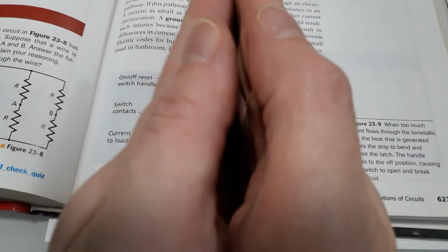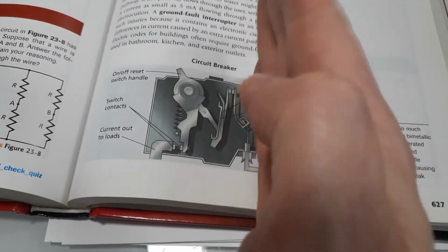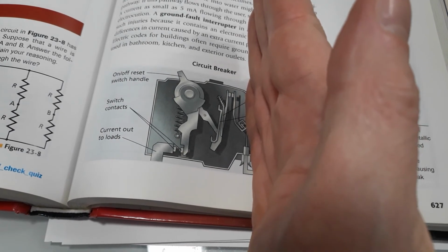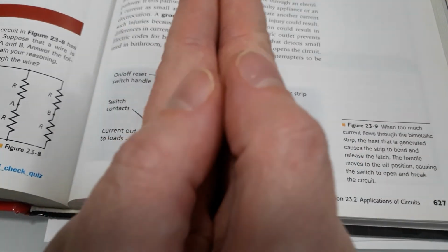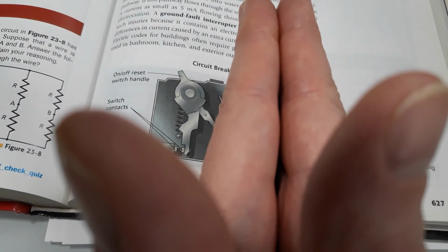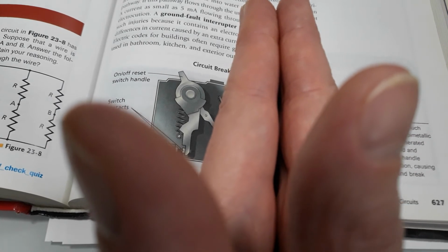So what you want is two different pieces of metal. Let's imagine that my right hand expands more rapidly than my left hand does. Well, when I connect these two together, even though my right hand is trying to stretch and get longer as it warms up, it can't go anywhere because it's connected to the other piece of metal. So as my right hand expands and my left hand doesn't expand as much, the piece of metal will begin to bend like this, because you can imagine my right hand is now following a longer path than my left hand is. Essentially, this thing is referred to as a bimetallic strip because it has two different kinds of metals.